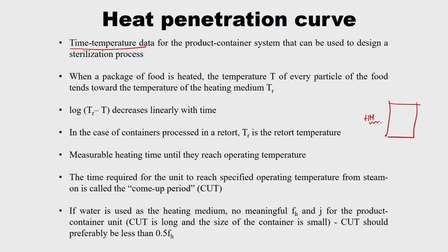From this, heat has to conduct or convect to the packaging material. From the packaging material it should reach the coldest point, right. Unless I know the time versus temperature data, I will not be able to design an efficient sterilization process. So, for that I need this particular heat penetration curve.